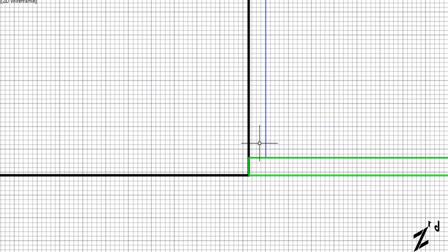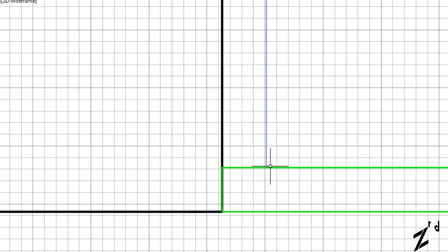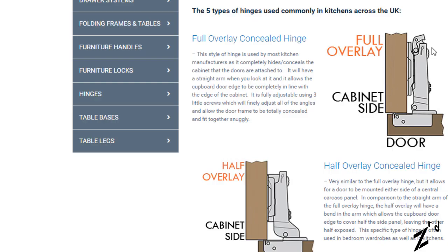This is the support. If you put a pin hinge anywhere here, the door simply won't even open. The mechanism simply won't allow for a pin hinge to open. But with a full overlay hinge, which is this particular one, you'll notice that the door comes till here and the rest of the hinge stays there, right? And that is connected to the side of your wardrobe, and this particular thing actually goes into the door itself.